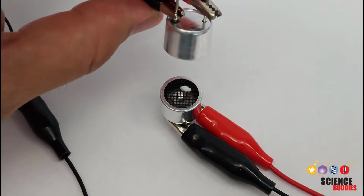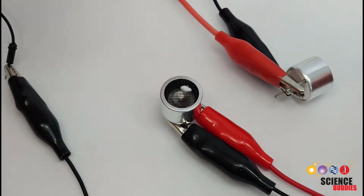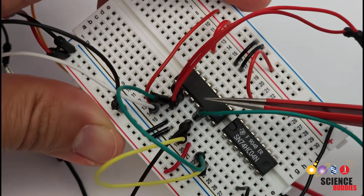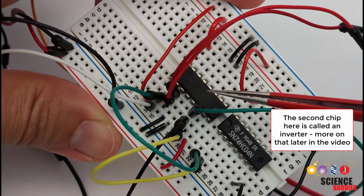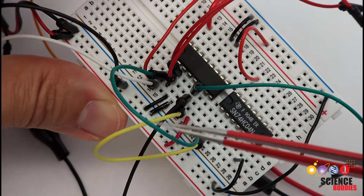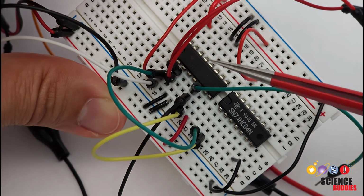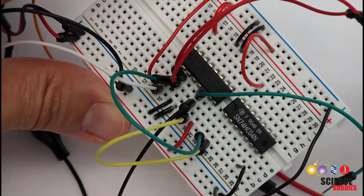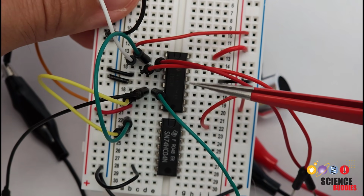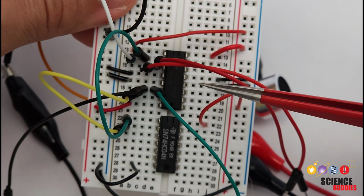To do that, we need a more powerful power supply for the transmitters, and that is where an electronic part you may have seen earlier in the video called an H-bridge comes in. Normally this part is used to drive motors or something that takes more power than the Arduino pins can provide directly. What it allows you to do is interface those lower power Arduino pins with a part that requires a bigger power supply or more than the Arduino can deliver directly. So as you can see, the wiring for this gets a little messy. We are going to switch over to the computer and a program called Tinkercad so I can take you through wiring it step by step.